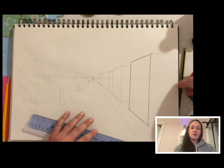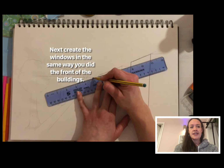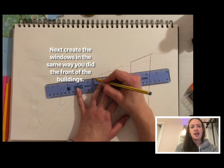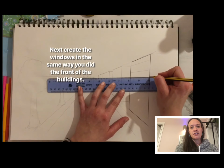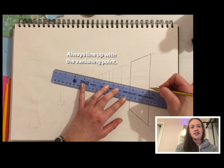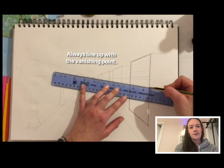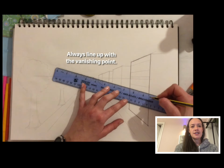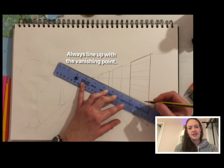So now I'm going to get the pencil to do my guidelines for my windows. Again, I'm doing the top of the first set of windows, and the ruler must line up with the vanishing point. Again, mark it, line it up with the vanishing point, draw the line. Now the top of the next set of windows, line it up with the vanishing point, draw the line. Bottom of the second set, line it up with the vanishing point and draw that line. And then the final set, the top of those, lining it up with the vanishing point. Same with the bottom.